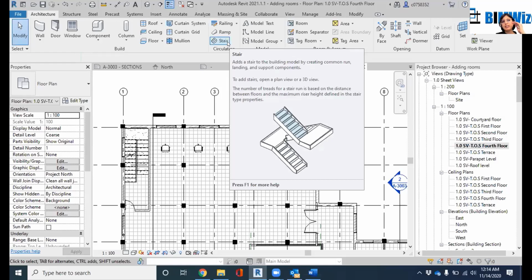And then you have to name your level. So let's say from your ground level or from your exterior grade level to your plinth level, it's 1.5 feet, and there are 3 stairs going. So you have to label each level so that from one level, you can pick up the other level. You know how we did the stairs, you do that and you will make 3 stairs.